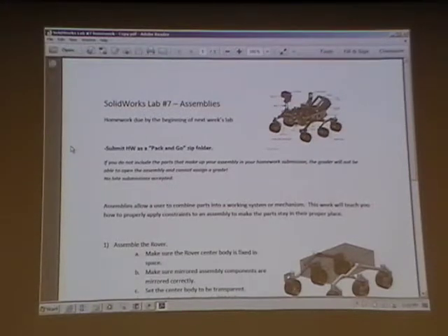And what's nice about sketch blocks is each time you insert a sketch block, SolidWorks lets you scale the sketch block to make it larger or smaller, and you can also specify an angle of rotation for that sketch block if you need to change its orientation.